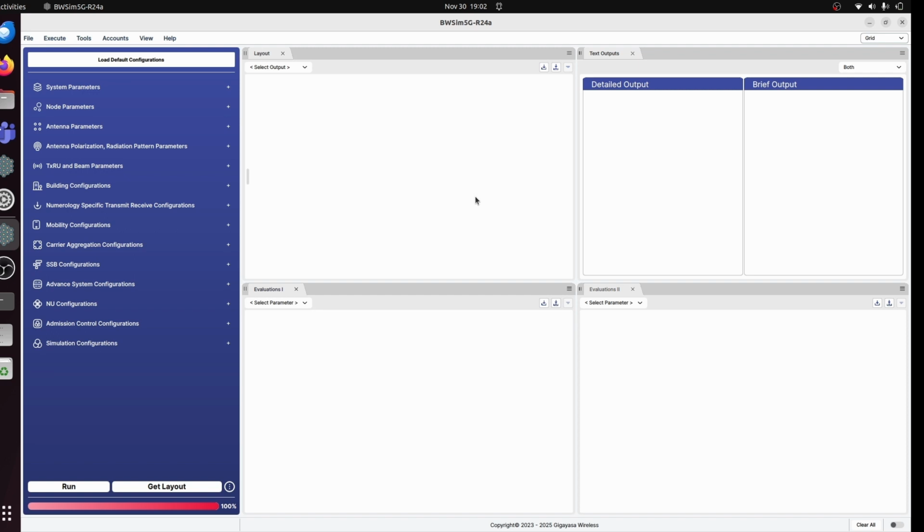Hence, the question of how to calculate path loss is very important. We do have a free space propagation model to calculate path loss. However, it may not accurately reflect real world scenarios. Consider the following example. You have a transmitter and two receivers which are equidistant from the transmitter. According to the free space propagation model, the path loss experienced by these two equidistant receivers should be equal. However, they would not be so in a real life scenario because of factors such as absorption and diffraction, which in turn are caused by the surroundings in which the receiver is present.